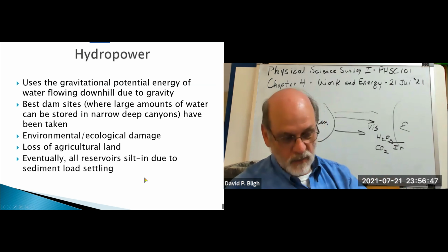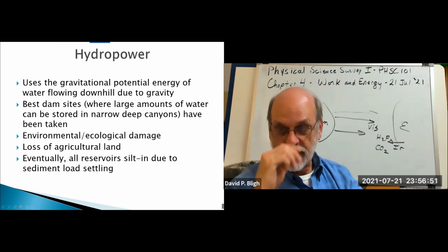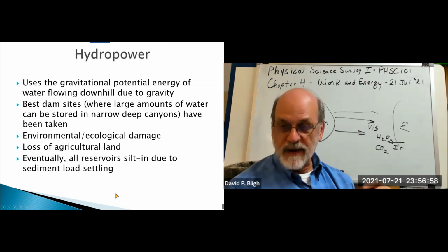In other words, the bottom will rise, which means that you can't store as much water in it, and you can't derive as much energy from it. So you have 2 choices. Either you abandon the dam at some point, or you go in and dredge it out.